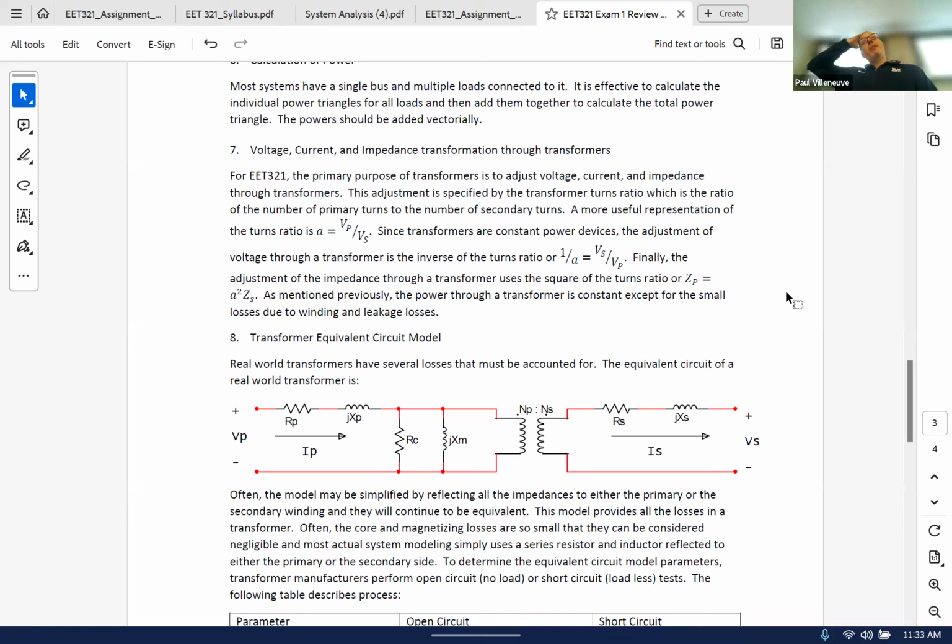because you're not putting any real power in the transformer other than the primary windings. So all that power, except for some of the losses, has to go into the secondary winding. If you were going to increase the voltage and the current through the transformer, you'd actually have some sort of other energy source to be able to do that. You're not stealing energy from the nether regions. It just is there.